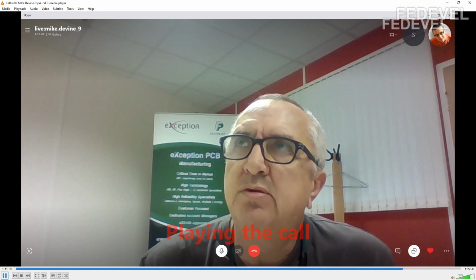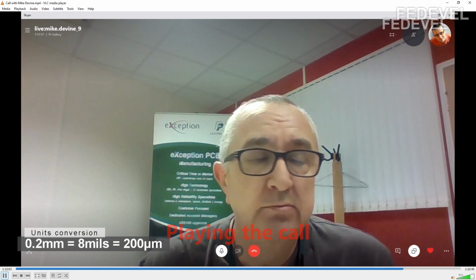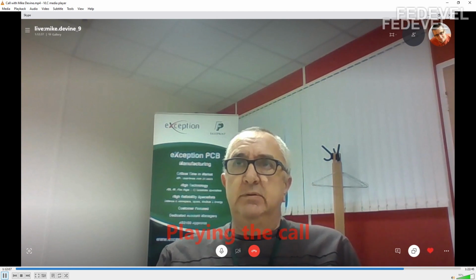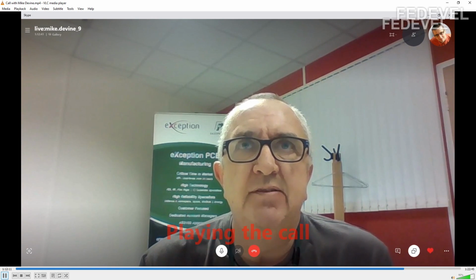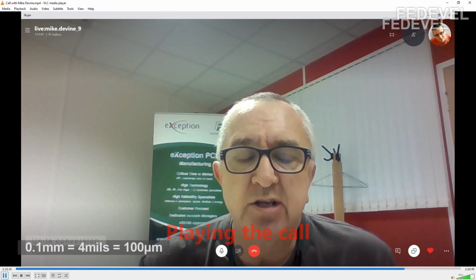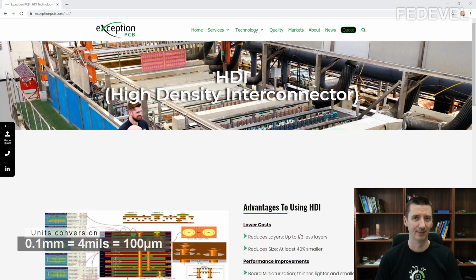Minimum hole to hole of 200 microns. For any kind of hole? Yeah. Okay. And if you have a buried via and a microvia tracked away from it, you can come down to 100 microns. So 200 micrometers between holes on your PCB.